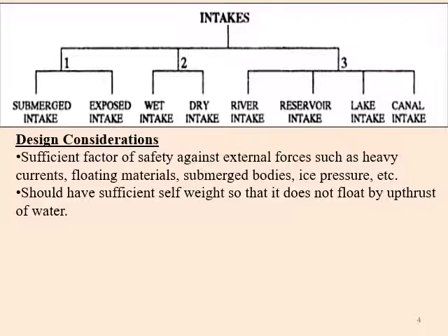At the bottom of the slide, some design considerations are written, like sufficient factor of safety against external forces like heavy currents, heavy flow of the water in the source, floating materials if present in the water, submerged bodies, ice pressure in hilly and mountainous areas, etc. These forces should be considered in the design of the intake structure, the concrete structure, and a sufficient factor of safety should be considered.